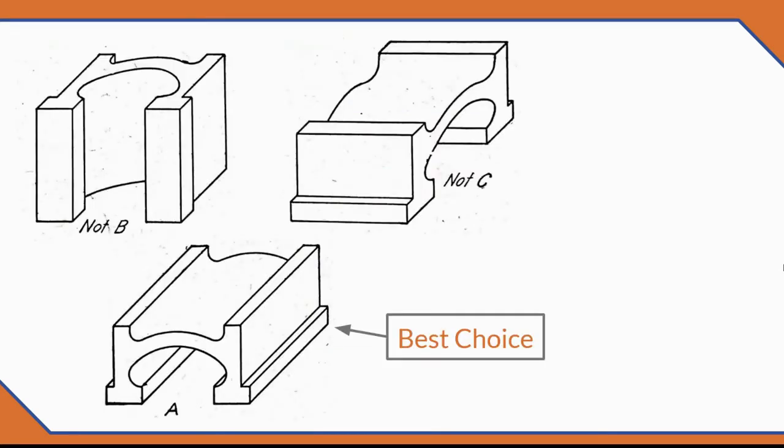As I said earlier, one of the advantages of an oblique drawing is that it shows the front-facing surfaces of an object without distortion, making them easier to dimension. This is especially helpful with arcs and curves because they can be tricky to draw accurately in isometric or perspective. So that means that when you're selecting the best front view for an oblique, it helps to choose the view with the curves. When the true shape of a surface is important, obliques might just be the best choice.